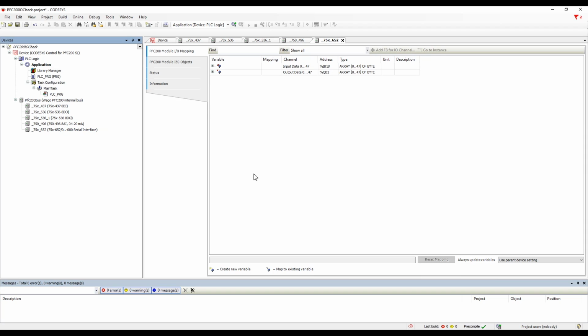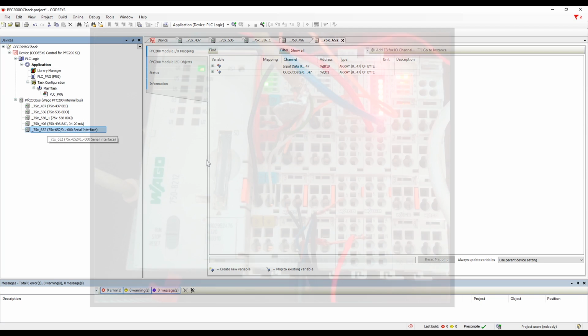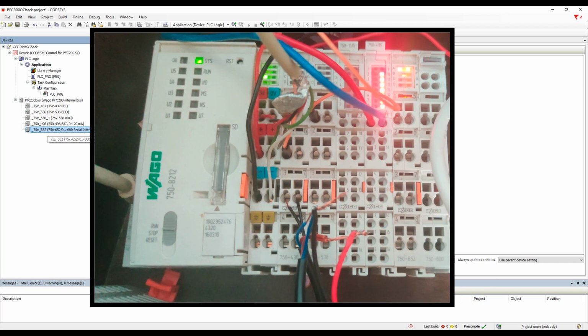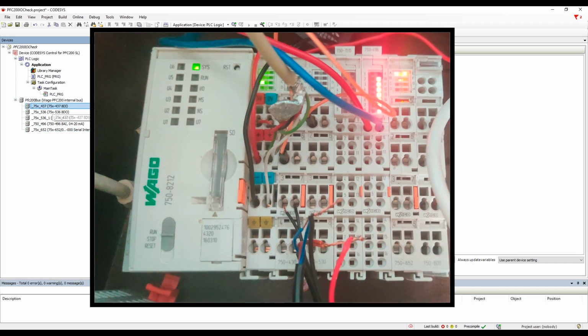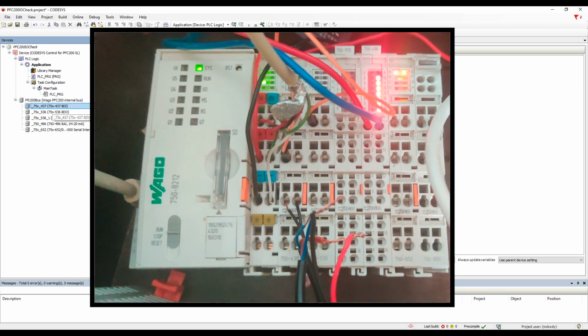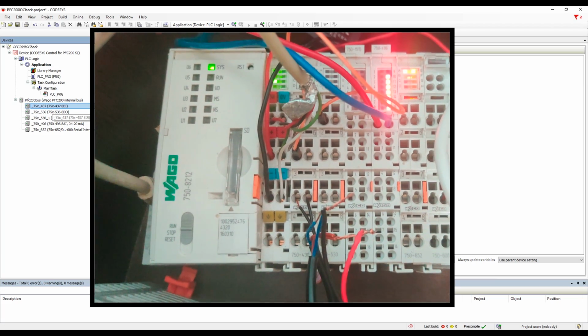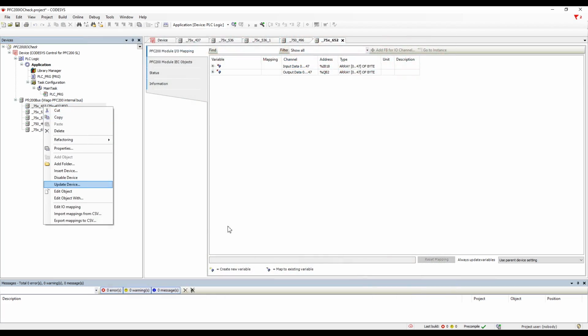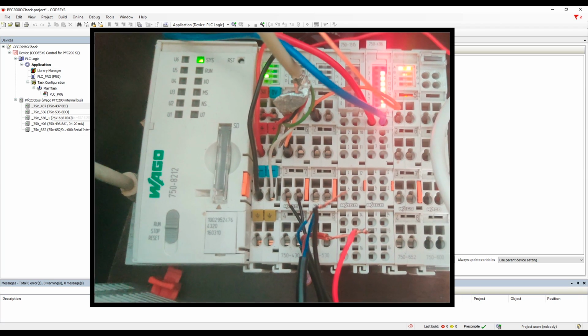Now let me show you how exactly the hardware configuration is done and how exactly the IOs are connected on the PLC, which modules are there. We will check whether they match with our internal configuration or not. If you can see, we have card 430 and card 530, but those are not matching here in the card configuration.